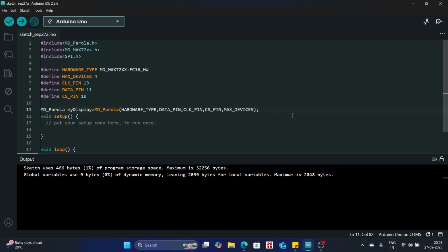Okay, and after that, to hold the string, we need some buffer. As you know, Arduino doesn't support strings. So what I'm gonna do is declare a character array, which I would call input character, with a buffer size of 100. Instead of defining it inside, I'm gonna create another variable so that we can use this buffer size in different places. So I'm creating a variable for this, and I'm saying max characters of 100.